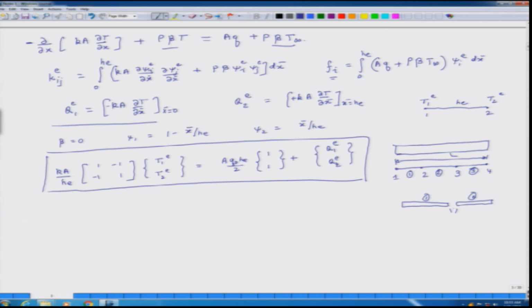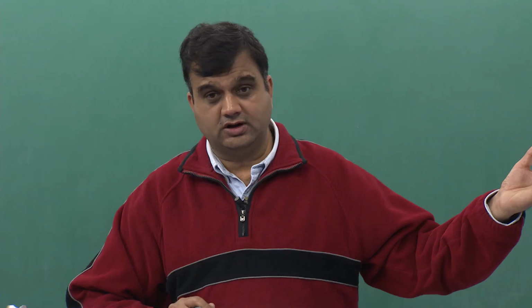So, the heat generated because of Q is expressed here, at node 1 and this is at node 2. So, the total heat which is being generated at this location will be contribution from this side and contribution from this side. So, I add up the contributions at the intermediate nodes from 2 elements. So, I add up the equations the same way we added up equations in case of solid mechanics problem, the same logic.